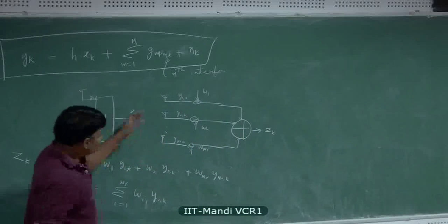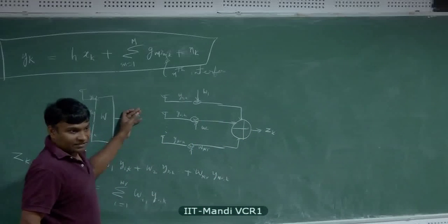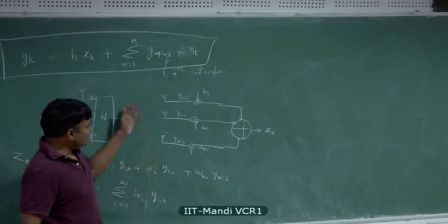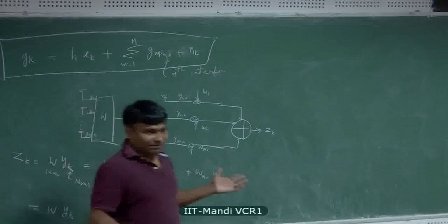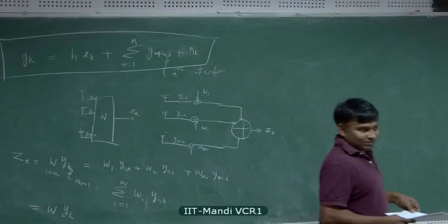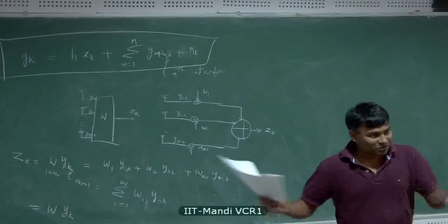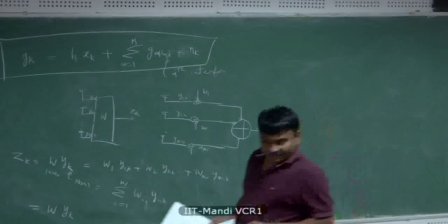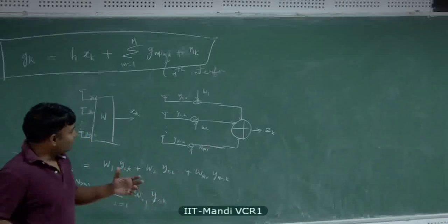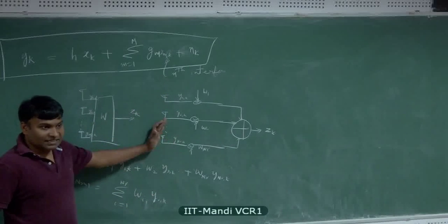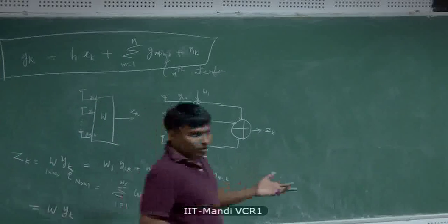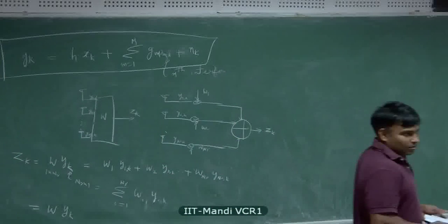Here you need multiple copies of the signal and interference in space. If you take multiple copies in time, they are highly correlated, nothing happens, because you get the same signal, same interference, and they are going to overlap. Nothing really changes here. So you need multiple copies of signal and interference in space. Why is that? Something is changing in space, right? The channels are statistically independent. We exploit that property to knock out interference.